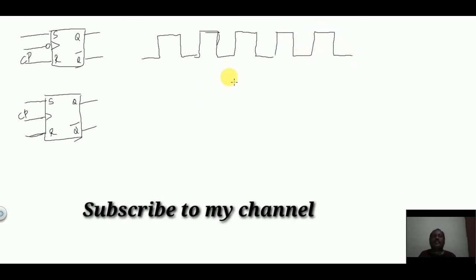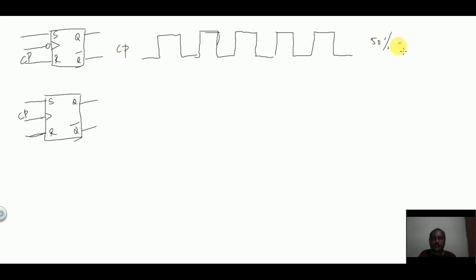A clock pulse is a rectangular pulse with 50% duty cycle, that means T on is equal to T off. So the off time period is equal to the on time period. Such a square wave is said to have 50% duty cycle. So a clock pulse is a square waveform with 50% duty cycle.